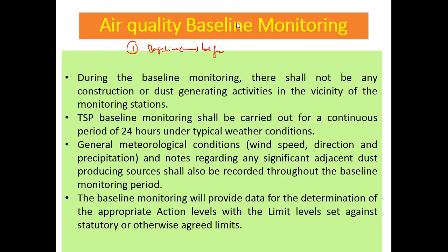We need to know what the existing air quality on that site is before construction activity started. So this is the baseline. When construction activity starts, the air quality must be on par with the baseline or less than the baseline.